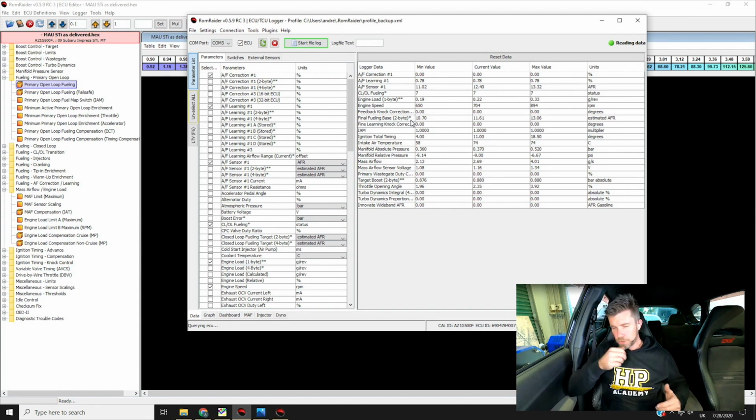Then we've got our boost control. So for our boost control, actually mass airflow, I haven't really talked about the specifics here. We've got two parameters here. We've got our mass airflow in grams per second, and then our mass airflow sensor voltage. So again, coming back to that, that's essential for filling in our mass airflow sensor scaling. Then we've got our boost pressure.